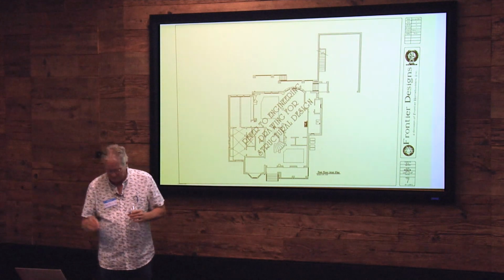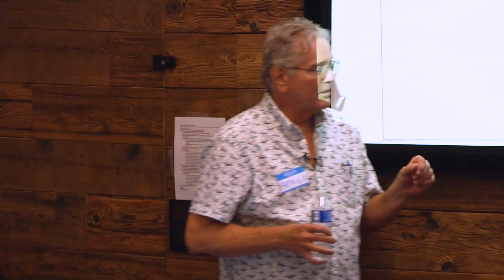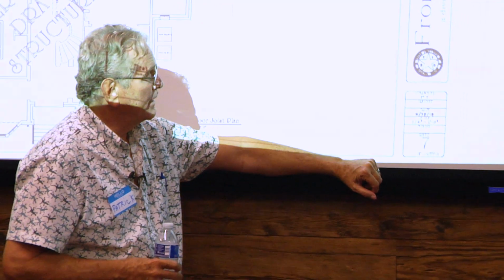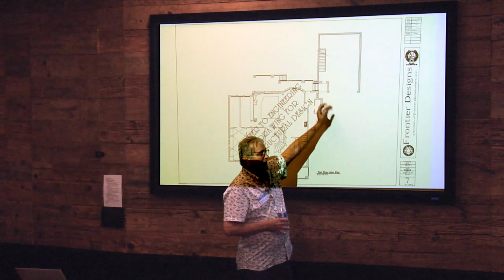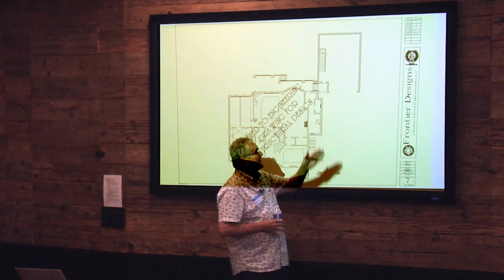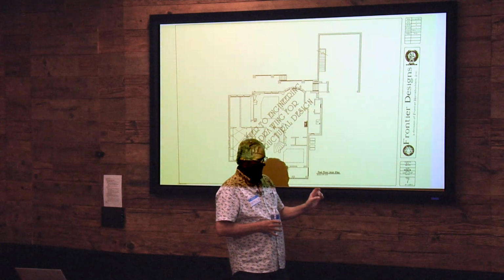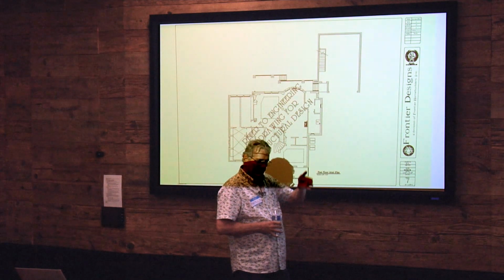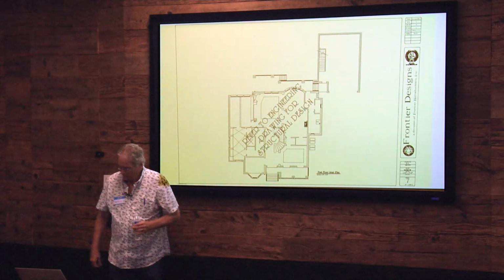Again, a lot of times those are just stamped on the plan and it's not ever used, but there are places to put numbers for revision dates down here. The sheet, what sheet number it is, that can come in handy when you look at not elevation, but cutaways on different plans. It'll show a line going through the plan and it'll be labeled A7 or something like that, which means you go to page A7 and you look for the cutaway. Those can be helpful, usually to the framers.